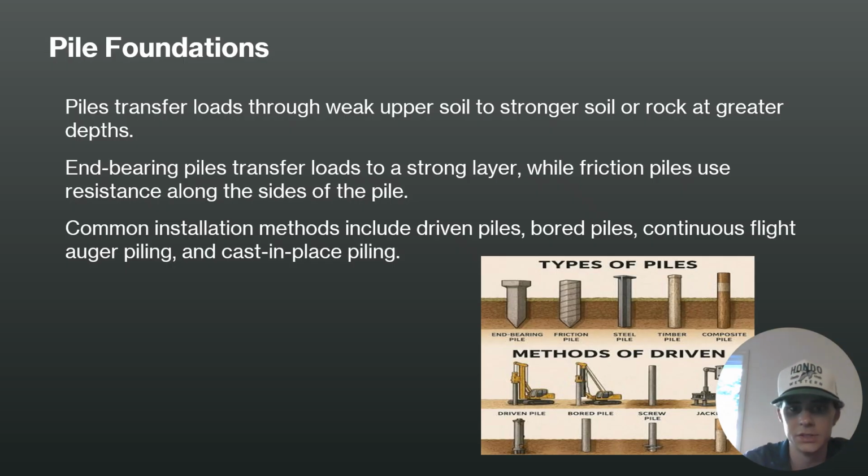There are also several installation methods that can be used when driving piles into the ground. Holes can be bored and filled with concrete, or other methods such as continuous flight auger piling can be used. These methods depend on the soil conditions, structural requirements, and characteristics of the job site.